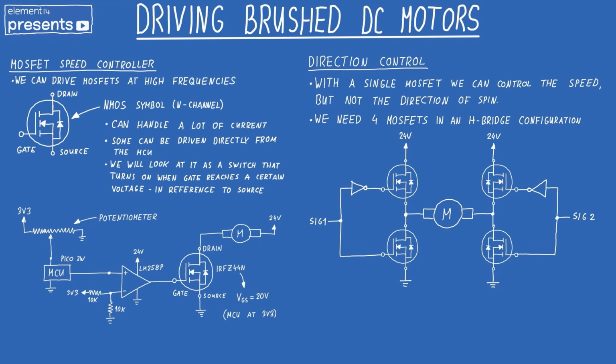The signals on one side of the bridge will never be high at the same time, since that would essentially mean that all of the current would pass through those two MOSFETs and not the motor. MOSFETs have low on resistance, so this would act as a short circuit, and we would pretty much fry the chip. This is why these negations are here, just to show that in the driving state, if one of the MOSFETs is on, the other must be off.